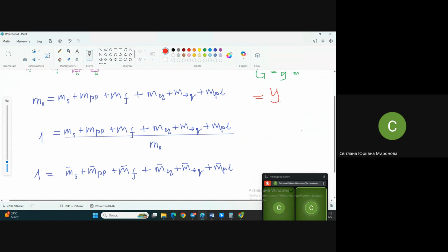No, actually, for takeoff, lift should be greater. To provide takeoff, lift should be greater. You understand? Because at this moment the speed is still insufficient, and you need more speed, which means a much longer runway, until you're moving along the ground for 20 minutes, for instance. Of course, it's not a good decision. Another way is to increase lift somehow, due to the power plant, high lift devices, and so on.